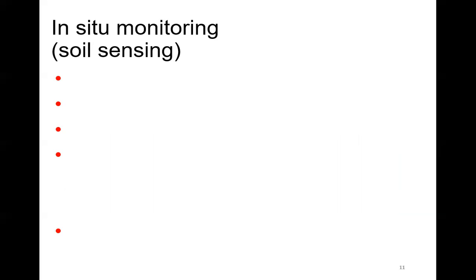Some of the things that we need to monitor, and these are all the things we've actually talked about in class, is obviously the in situ total stress. So this is our sigma. We found ways of estimating this using our gamma, right?